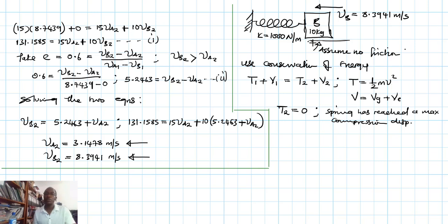Then at this particular point, we expect V1 itself to be equal to 0. We don't have any gravitation because at this point, this spring is at rest, right? And then what about V2? So V2g is equal to 0. All right, but we do have our V2e just going to be equal to half k s squared. So we'll have that one.